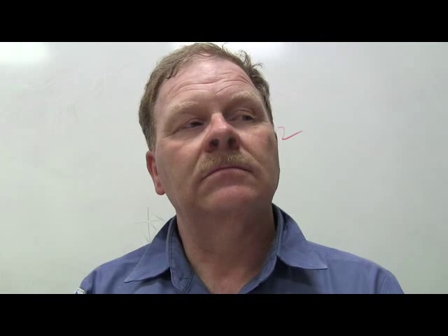All right, let me see. Refrigerant enters the evaporator as what? A low pressure atomized liquid, a high pressure gas, a low pressure vapor, a high pressure liquid? What do you think? Is everybody in here just waiting to have the answer spoon fed? The refrigerant enters the evaporator as what? Now, why would you do that if it needs to evaporate? Low pressure vapor? A low pressure atomized liquid, because it needs to evaporate, right?